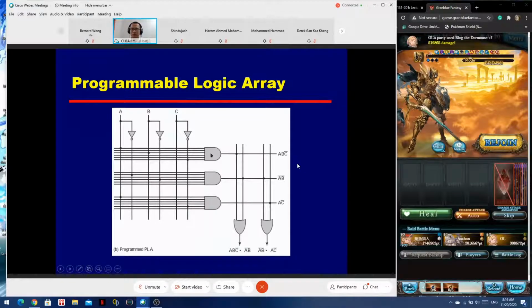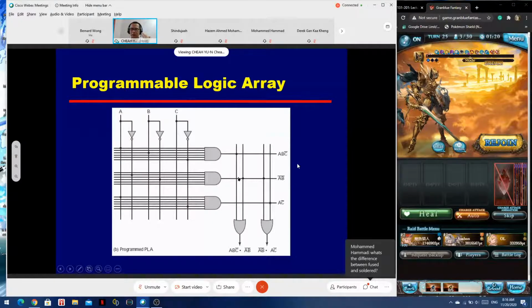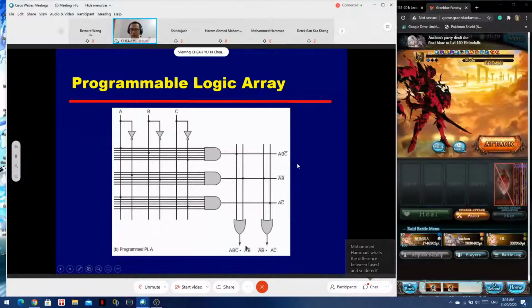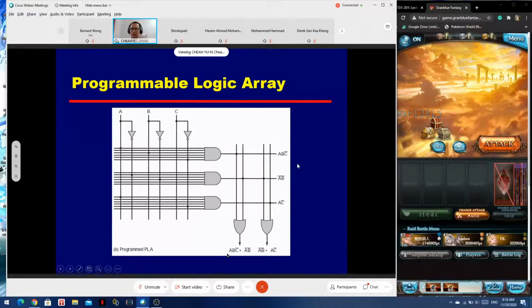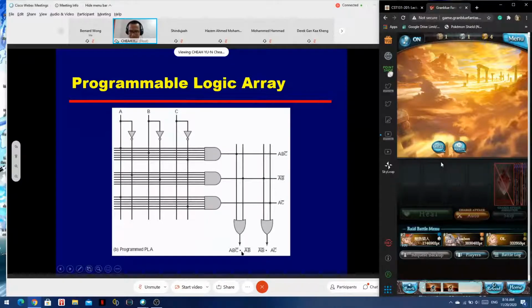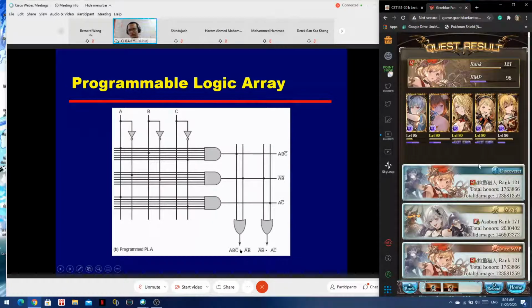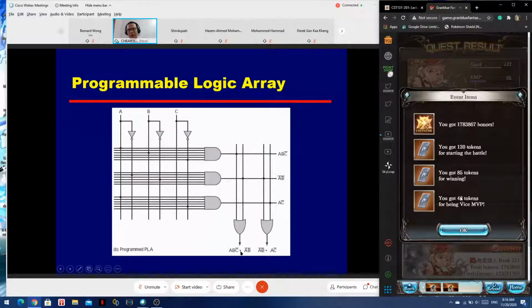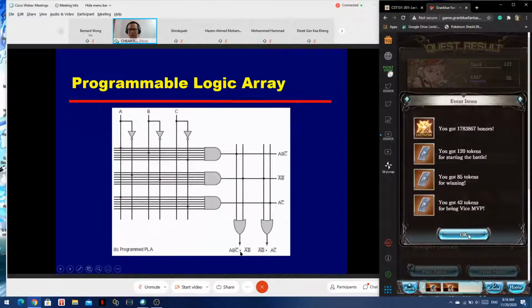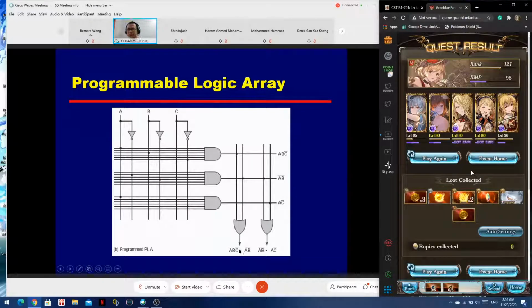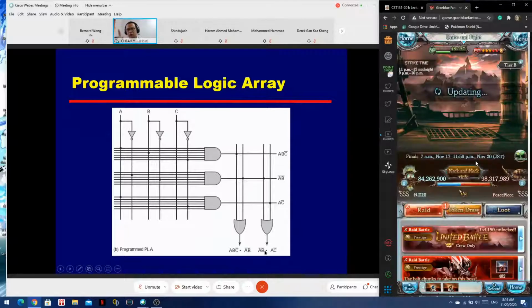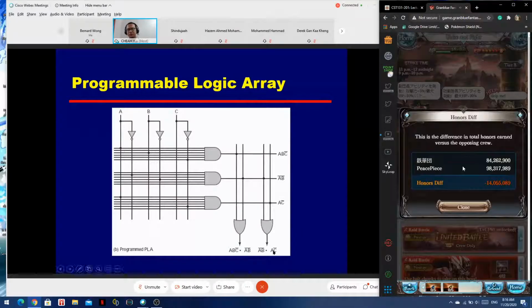So that means we will take the AB not C and we also will take the not A not B. So that's why here you will notice at the bottom, this function will be AB not C or not A not B. Okay, there's a little bit of a diagrammatic issue. I've taken the image in total, but I didn't correct the notation here. This dot here should be the OR sign. It should be the OR sign. Similarly for the other one, it should be not A not B or not A not C.